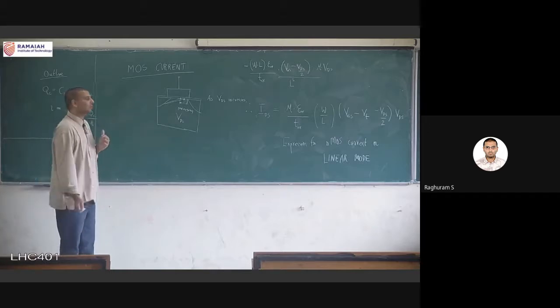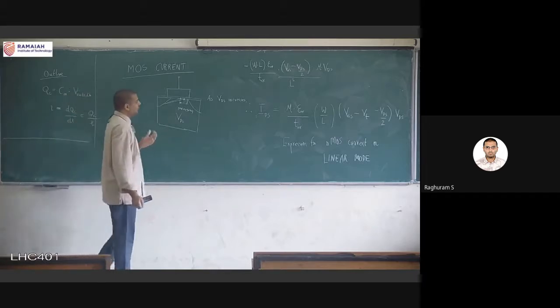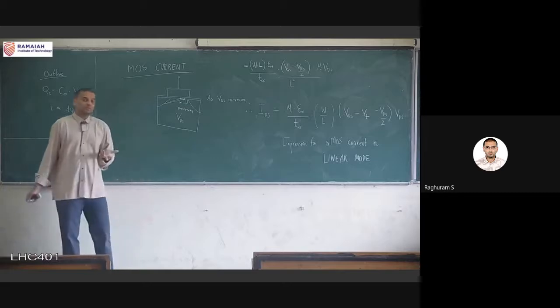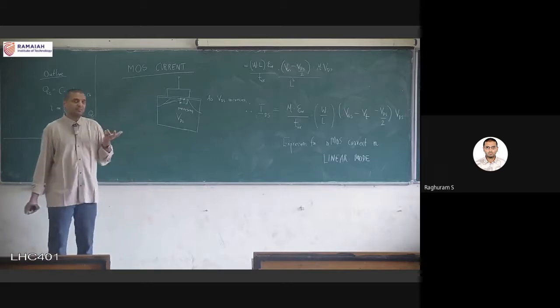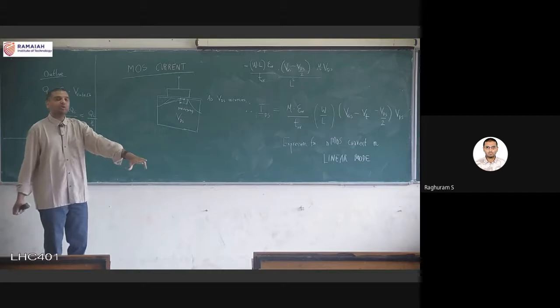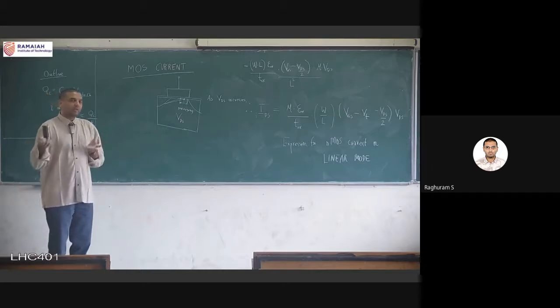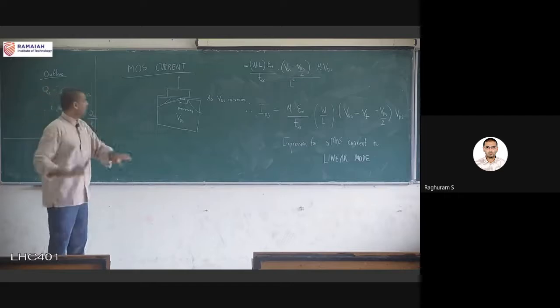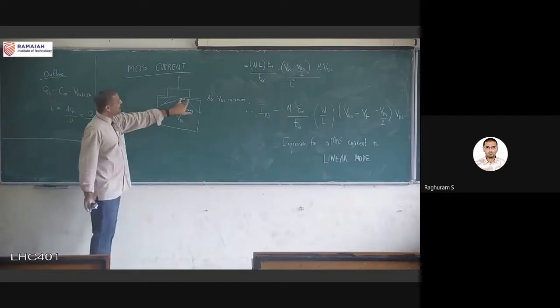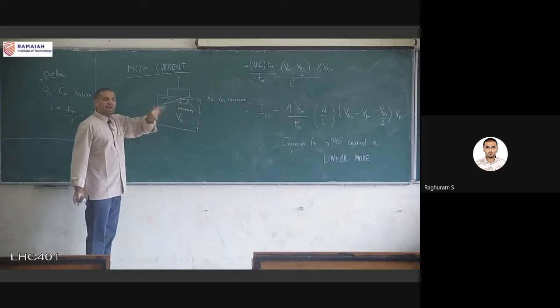That is why in some ways this mode of operation is also called saturation mode. You can keep increasing the VDS, but the current is not going to increase. VDS, for example, you can divide into the excess VDS, which is going to appear in this region, and the actual component of the VDS that is responsible for this electric field.